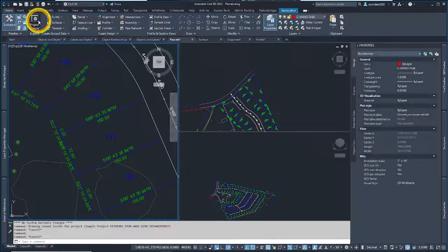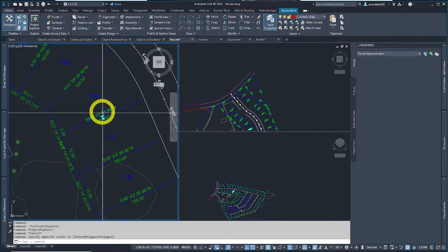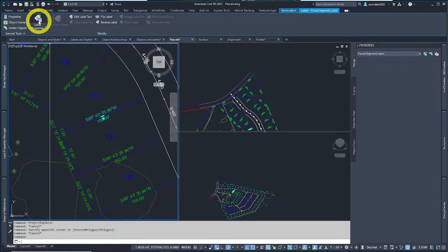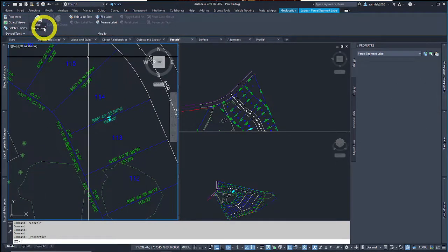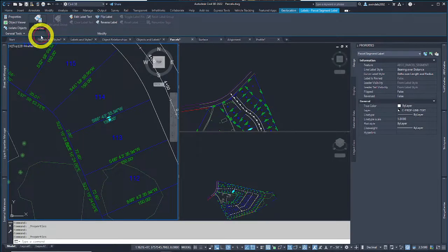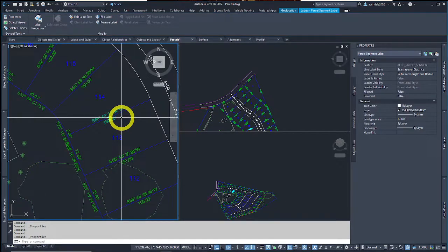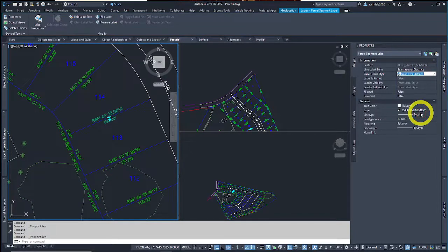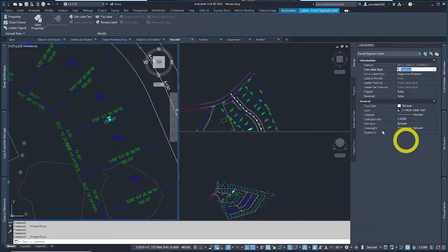There's a few ways. It's a little confusing at first and overwhelming, I know. So we're going to start by one at a time. I'll pick this label. Let's go to our contextual ribbon, edit the label properties, give it a second. I had to go down to this one, my bad. Alright, anytime now, Civil 3D. Oh, right. Since this is a label, a lot of times they don't open the same way. Sometimes you have to only change them here. So I'm going to change the label here to slope over distance, for example. The line label, just a distance.